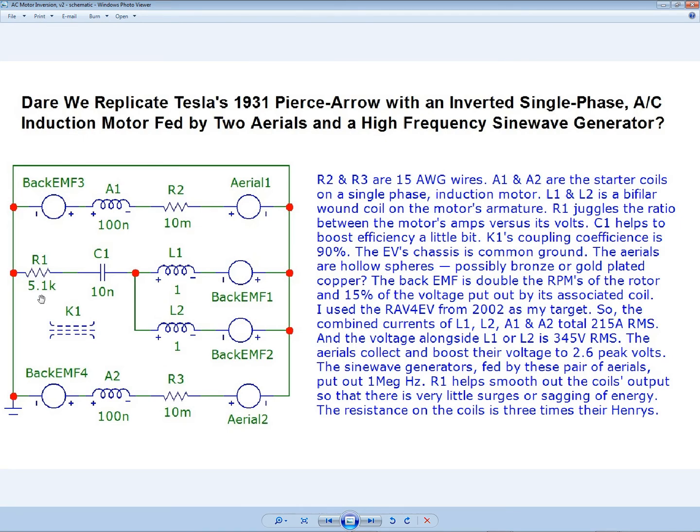Well, I was operating the circuit without a load. And it turns out, though, a load can do different things depending on where you put it. For instance, what kind of load. In a sense, an inductor is a load. L1 here and L2, those are loads. But the placement of these two inductors here is actually an area of negative resistance. Everything along the midline, the middle portion here, is a negative resistance area.